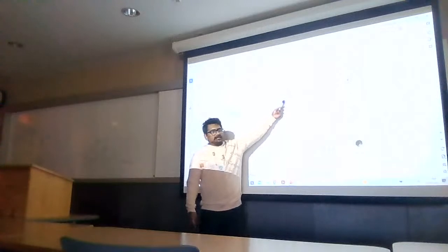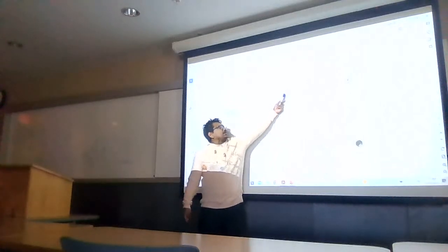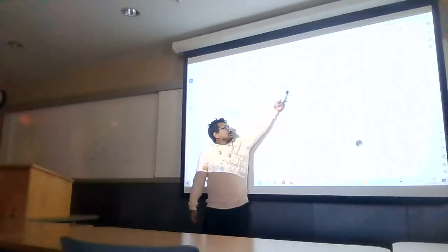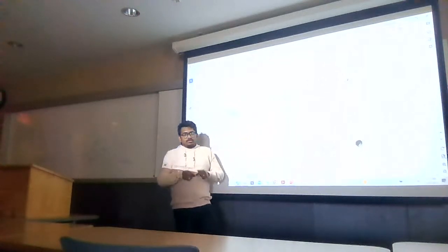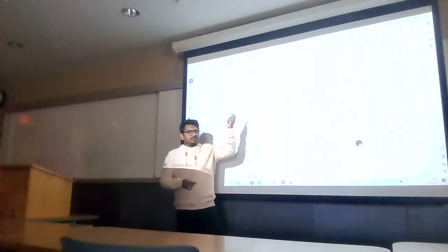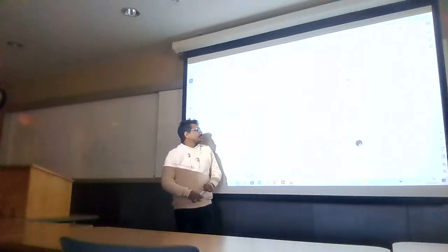If I change a little bit in VGS, then there is also a change in my current ID or IC, whatever you say. It means that this curve is not linear, it's an exponential curve. So this is the mathematical expression of GM.